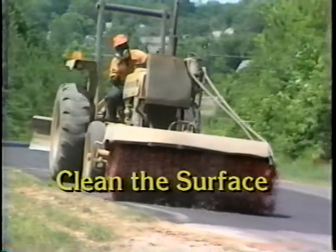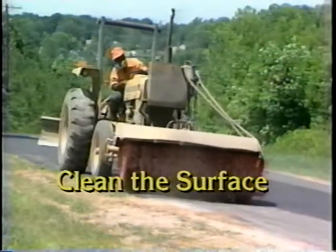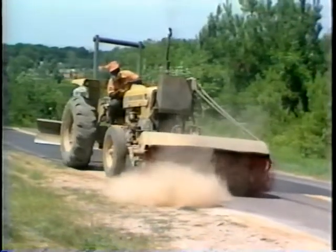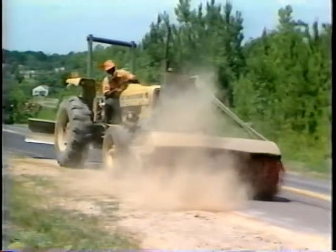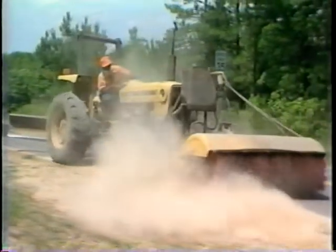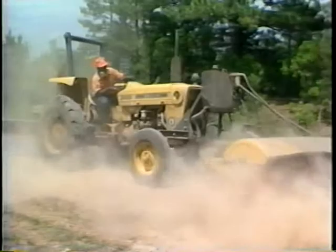The third step in the asphalt chip seal procedure is to clean the surface. Clean the surface prior to spraying asphalt. Cleaning is usually performed with a tractor-mounted power broom. This is effective for removing loose sand, stones, and debris. Remove hardened mud and other foreign matter before the seal is installed. The objective is to provide a clean pavement surface for the asphalt to bond with.